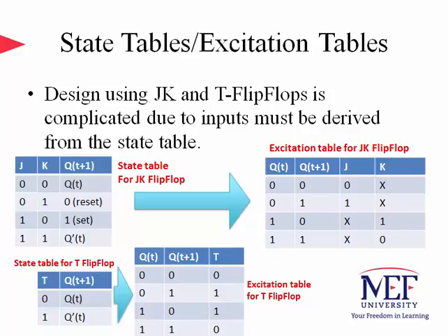flip-flops. However, JK and T flip-flops provide more freedom, and using this freedom we can end up with less combinational logic added to our sequential circuit design. Plus, most of the time JK and T flip-flops are cheaper compared to D flip-flops. We'll see an example to support these arguments and comments next by walking through a real design example.